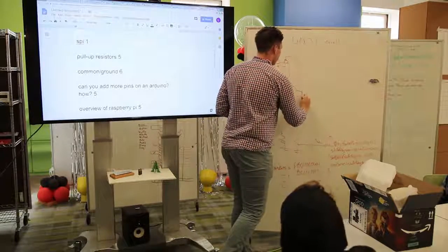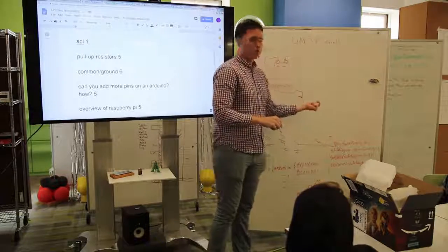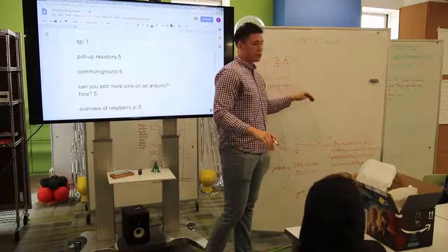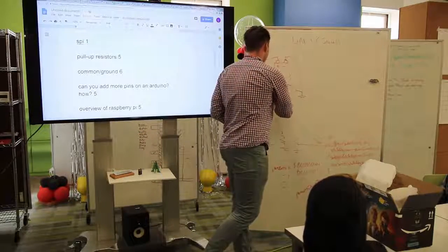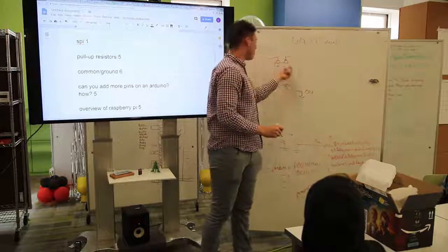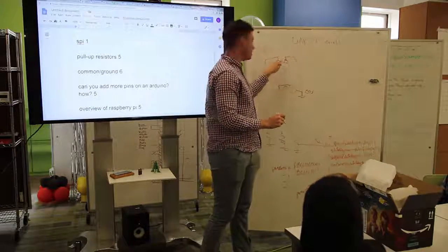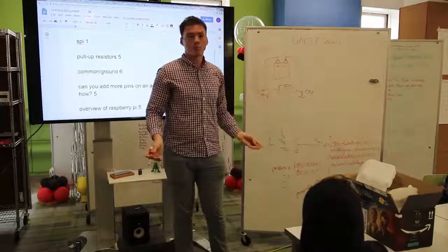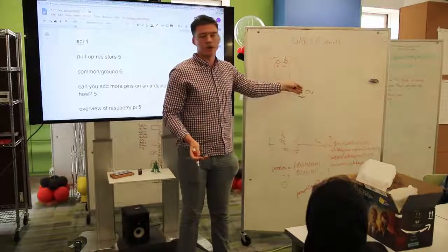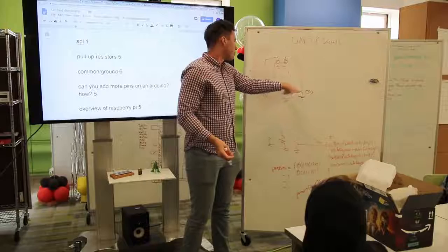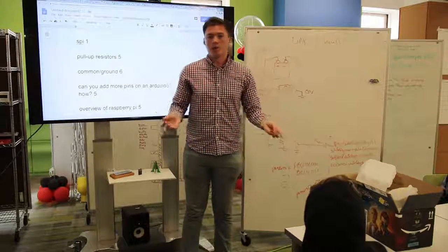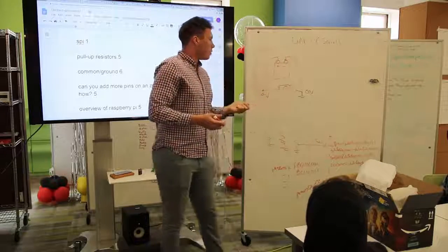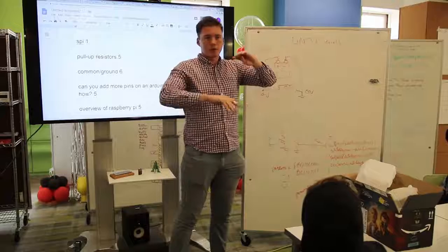So ordinarily I would just drop this right here. This means ground. And that means I've now defined voltages for everywhere else in the circuit. So basically what I'd say now is, since this is ground on this side, this is 0 volts. Well, the difference between these two is 9 volts, so this node has to be 9 volts now. It can't be anything else. Previously, like I said, I could have made it 1337 and this one 1328, and that would have been totally valid because the difference between them was 9 volts, but it doesn't make sense because it just makes everything else really annoying and difficult to read. Does that make sense sort of in terms of difference and what ground is used for?